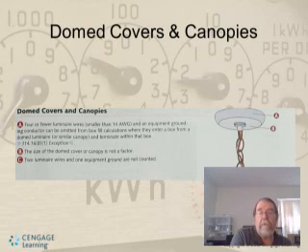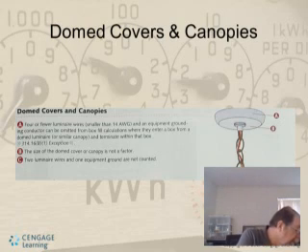Now, the conductors going through there, you still have to count those conductors. If there's an incoming feed coming in, and then you're going out to the next light fixture in the ceiling or something, then the incoming conductors and the outgoing conductors have to be counted.